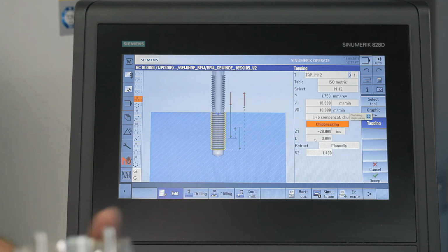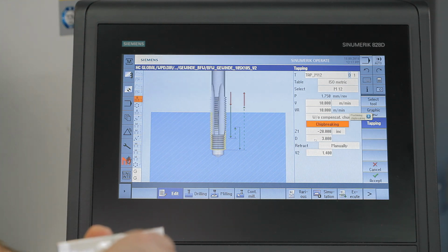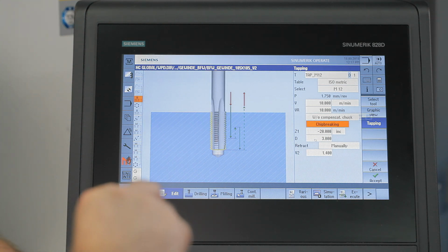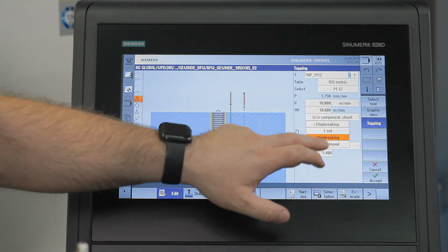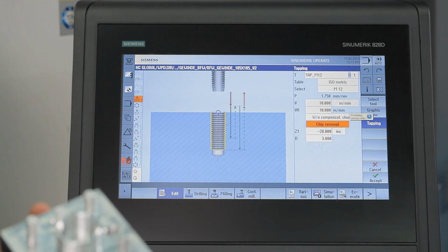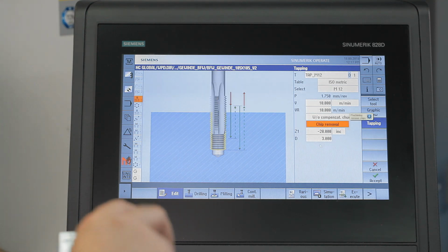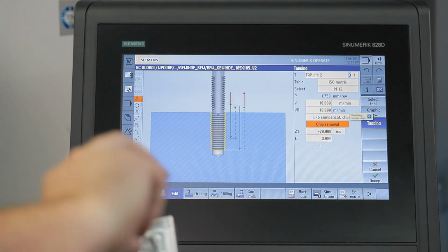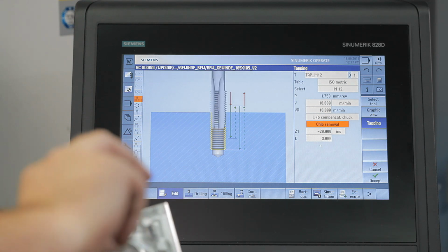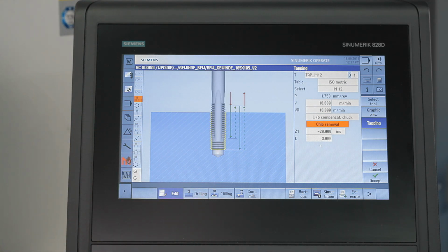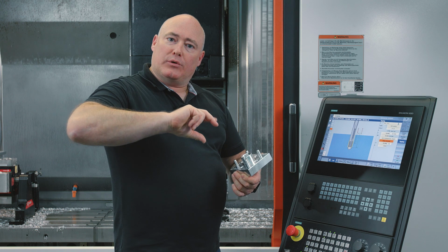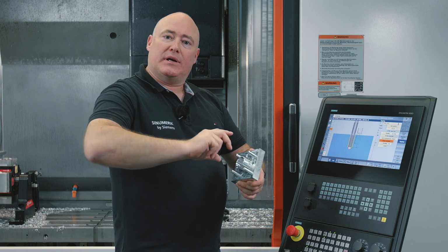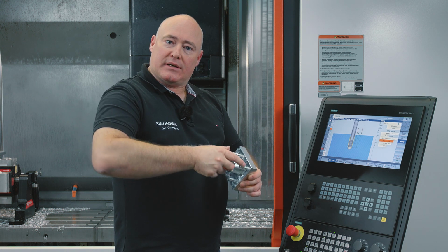The tool is inserted a certain distance, stops briefly, and then is turned back a short distance before continuing into the thread. The chip removal cycle functions somewhat more efficiently. The tap is inserted into the material, then completely removed again, goes back in and out again until the final thread depth is achieved. Here too, as already mentioned in the theoretical part, synchronization of the spindle and the feed rate permits repeated insertion into the thread.